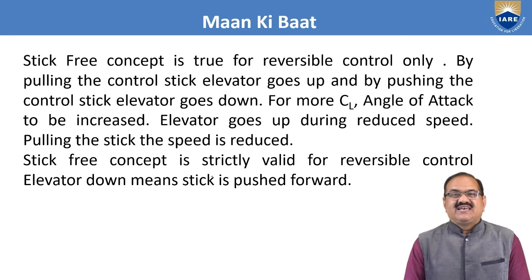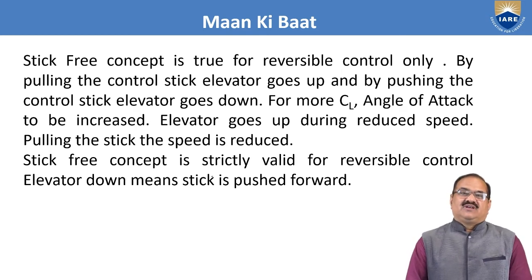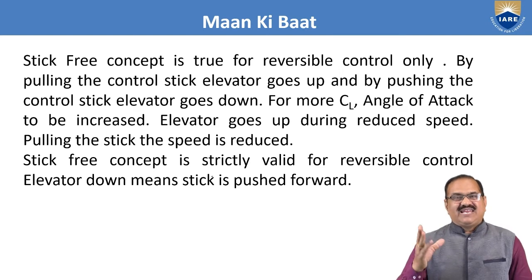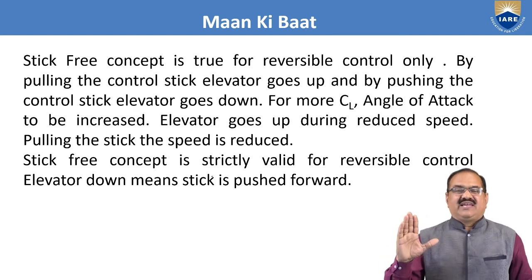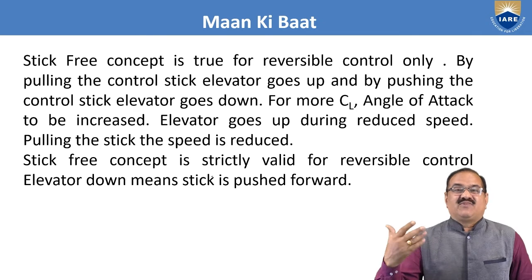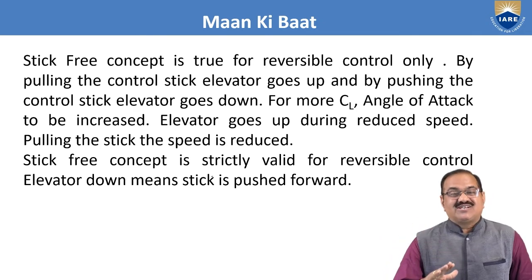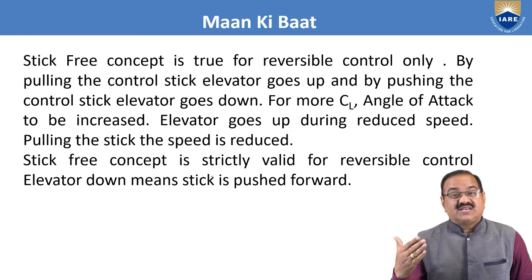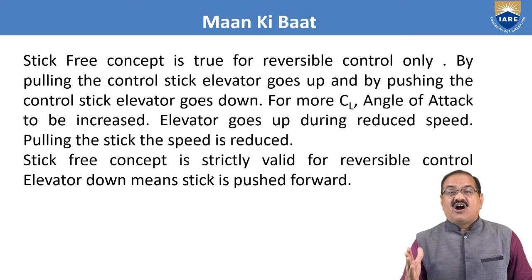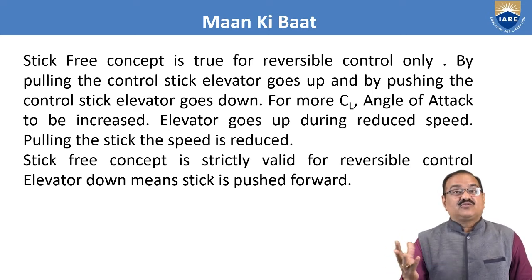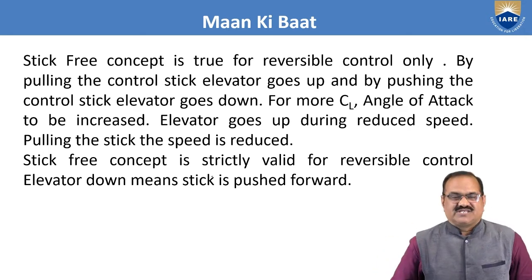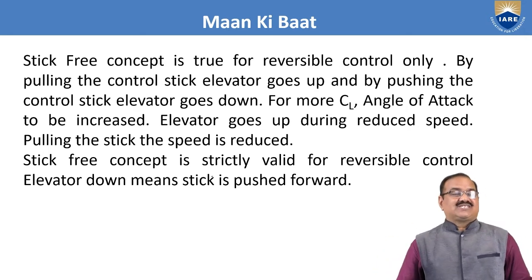Stick free case tells about how much floating of the controls happens due to aerodynamic effect. Whenever any airfoil is flying, it will generate some force. This force we have not considered in our stick fixed case. But in the stick free case, we have to see how much force it is developing, so that much force the pilot has to apply to counter the aerodynamic forces. Here we are going to discuss all these issues.